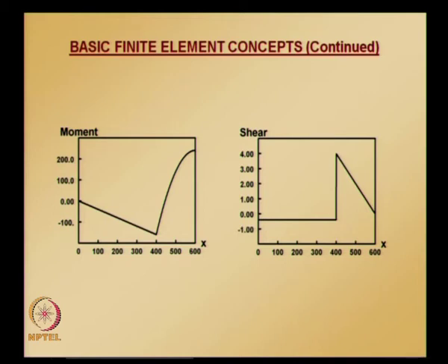And shear force similarly, from x going from 0 to 400 is coming from element 1, and 400 to 600 is coming from element 2. So, so far we have concentrated on computing displacements, bending moments and shear forces for both kinds of loading, concentrated loads and also distributed loads.